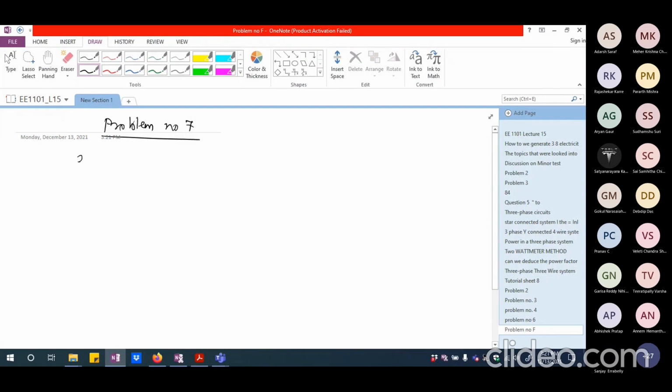So this says 240 volts is the line voltage, or the voltage in the delta connected load, and that is 20 angle 80. So if I want to calculate the magnitude of phase current, I should say 240 divided by 20. If I just say what is the magnitude, this is going to be 240 divided by 20, which is 12 ampere.